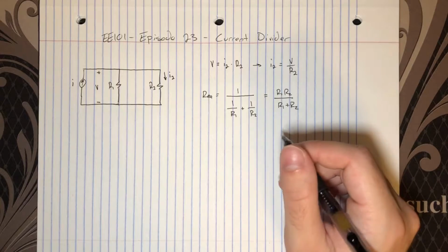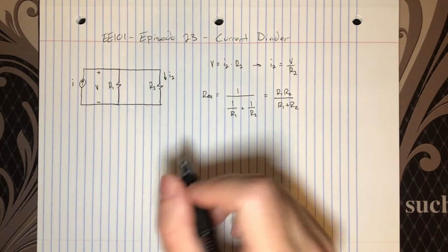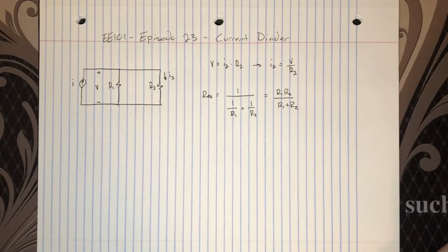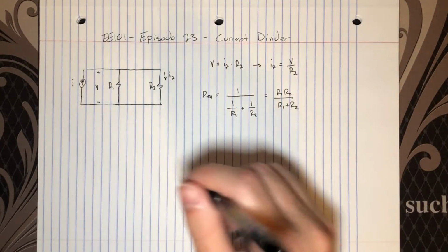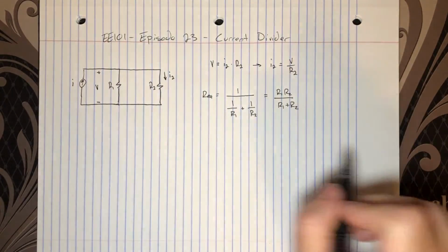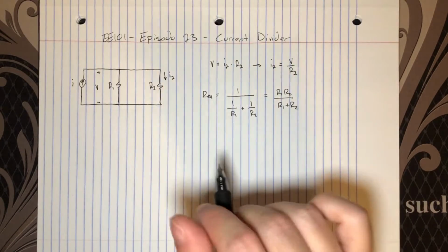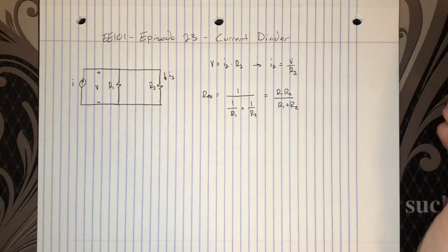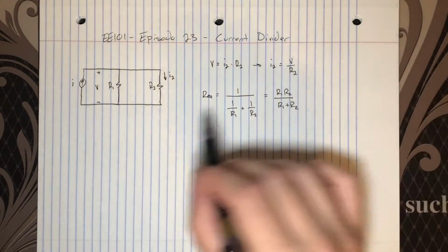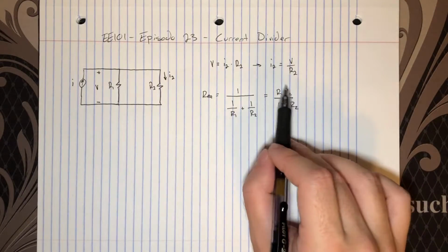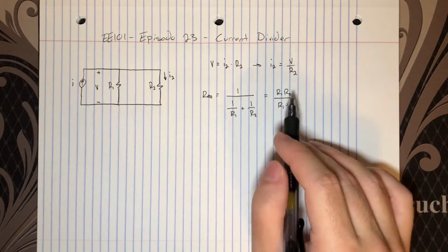And same thing in series, because resistors just add in series, right? And you're just adding numbers at that point. So if I'm adding up 10 numbers, I don't have to add them all at once. I can add the first two and then add that to the third one, and then I can just add one at a time. And so that same concept applies with parallel resistances. You can just work two resistors at a time, and it allows you to use this nice, cute formula.